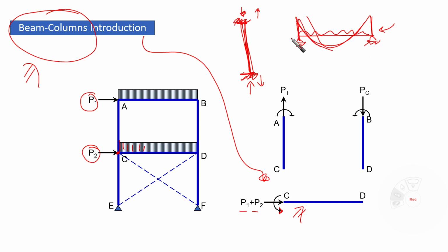We said that there might be small axial forces due to friction or some restraint at the end supports, but we said these kinds of axial forces are going to be neglected, and they do not contribute to the main straining actions developed in this element. Based on that, we said it is called a beam, and officially we call it a flexural element. So you can call it beams, girders, anything, but it is a flexural element in general.